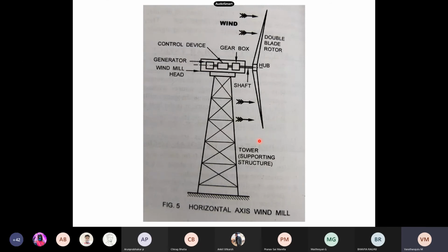the single blade. Here the double blade windmill is provided in this picture, and the windmill head is mounted on a bed plate attached on the top of the tower. The windmill head accommodates a step-up gearbox in order to increase the rotational speeds. We also have the control device and generator, or subsequent devices, in the windmill head. The blade rotor drives the generator through the transmission gearbox, and the two blades have a thick cross section of an aerofoil made of aluminum or sheet metal.